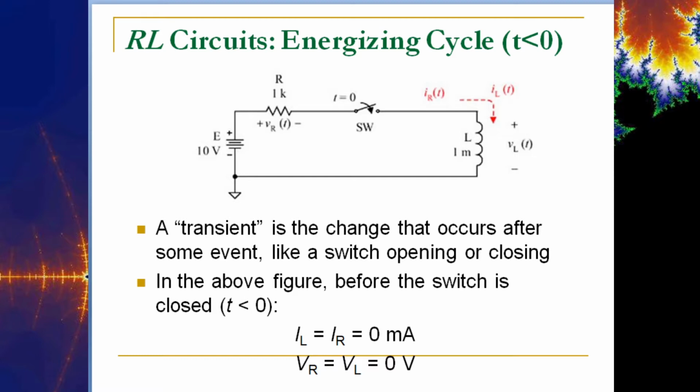The opposite is going to happen with an RL circuit. We're going to have all the voltage initially on the inductor, and then it will essentially be released over to the resistor. It's not really released, but the circuit will reach a steady state value for current, and that happens at 5 time constants, just like with the voltage regulating itself on the capacitor.